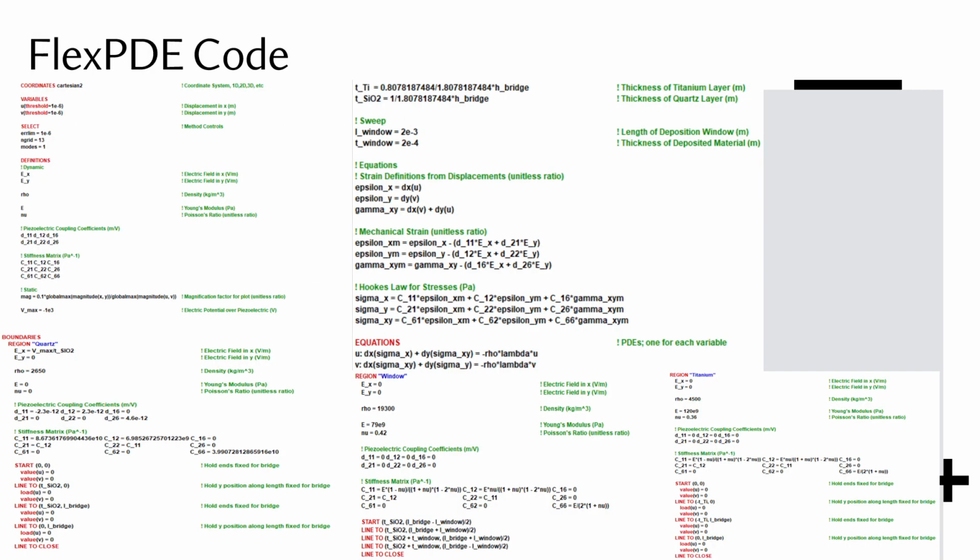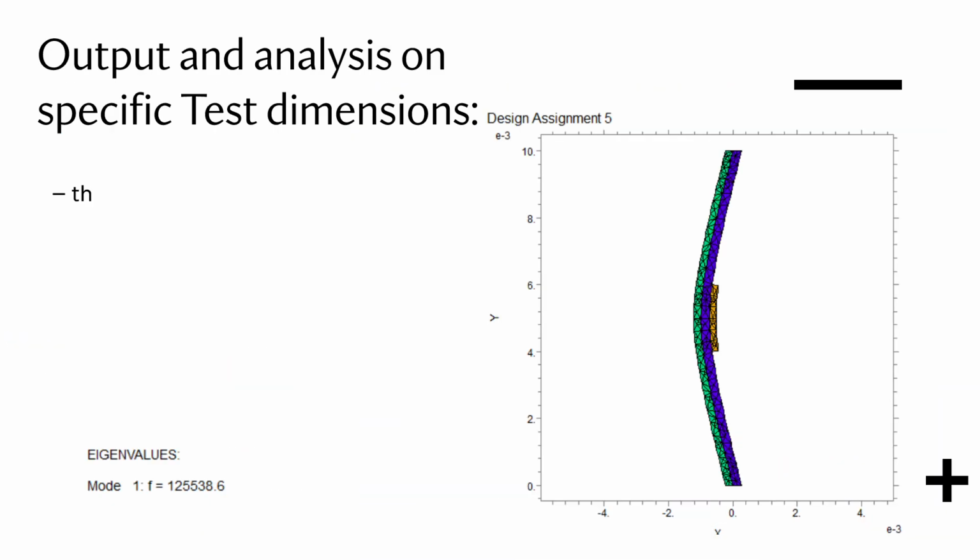The model developed for the QCM resonator can be validated through several methods. Firstly, the piezoelectric portion of the resonator can be validated by running electric current through it and observing the resulting vibrations at a particular frequency. The frequency should remain constant regardless of changes in the voltage, but can be affected by the material properties and thickness of the layers. Secondly, the structural aspect of the model can be confirmed by fixing one end in the y direction, allowing the X section to be free to slide, as seen in the plot.